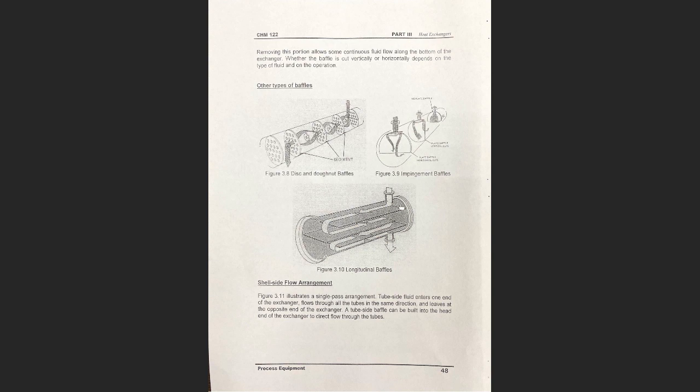Instead of having, for example, a tube 20 meters long, you have a tube 5 meters long and you have 4 passes. The fluid enters right to left, right to left, 4 times before it exits. If the length of the tube inside this exchanger is 5 meters, in each pass, it would be equivalent to an exchanger with 20 meter tube length. But of course, an exchanger with a 20 meter tube is very difficult, so they use this design technique to reduce the tube length.